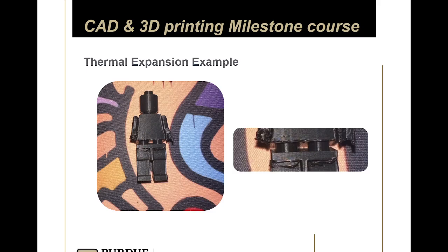What I mean is that one side should have been slightly smaller, or the other side slightly bigger. If you have zero tolerance, then when you go to put things together, it's not always going to fit, right? The prints aren't exactly the dimension that you set in the CAD, so you might want to undersize or oversize things a little bit.